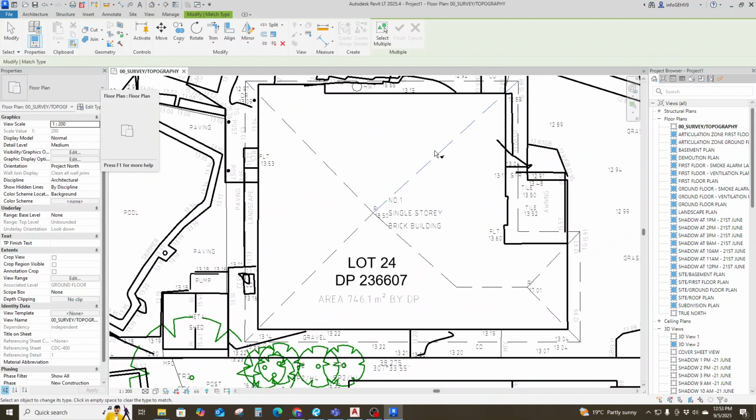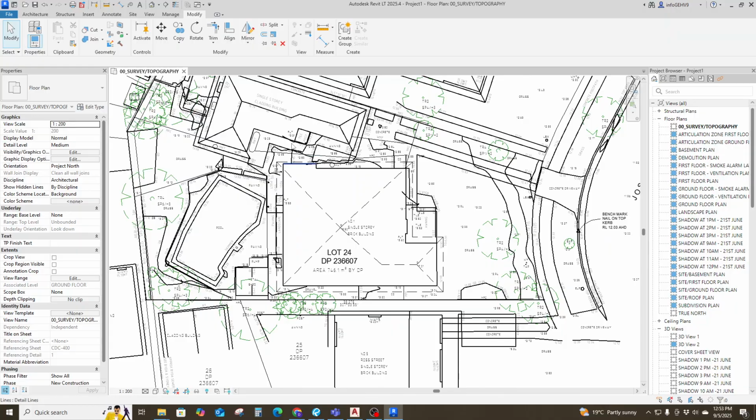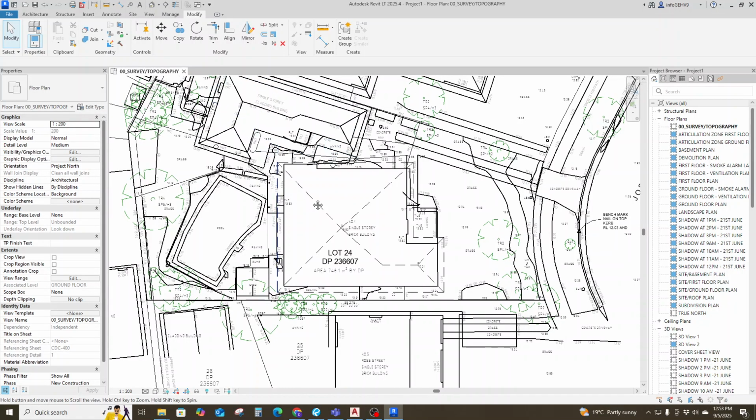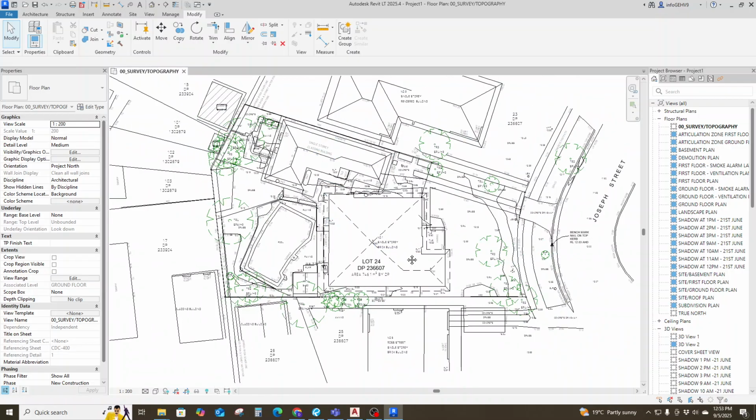Okay, I think we have done the roof of this one, and then you can just escape. The best thing to do would be to open the PDF side by side to check which ones are roof, so you do not miss any line. So you can fix the roof like that.